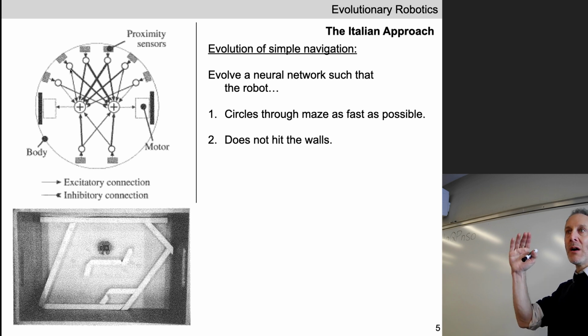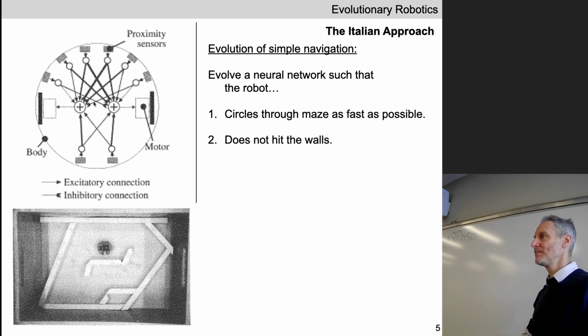Signals that go from the left sensors to the right motor or from the right sensors to the left motor, actually, you can see a little bit better here. Let's follow this one. That's an inhibitory connection. The contralateral synapses, across sides, are inhibitory. Why did they choose that? I believe it's because that means if an obstacle is closer to one side, it will turn away from that obstacle. So they're building in a little bit of Braitenberg's coward vehicle, right?